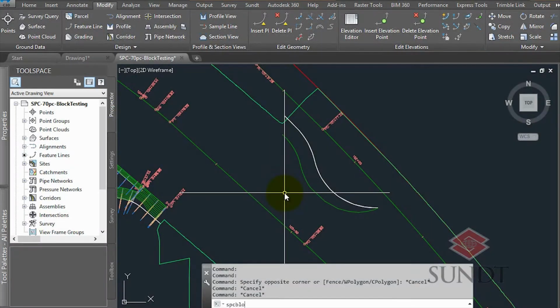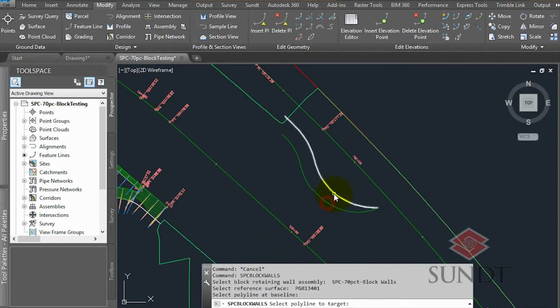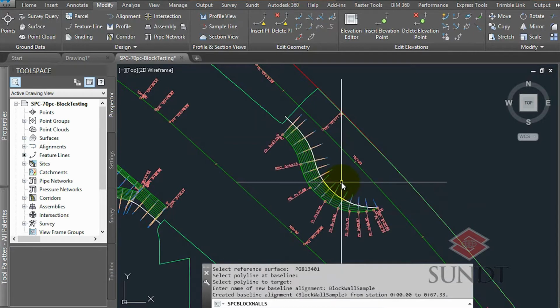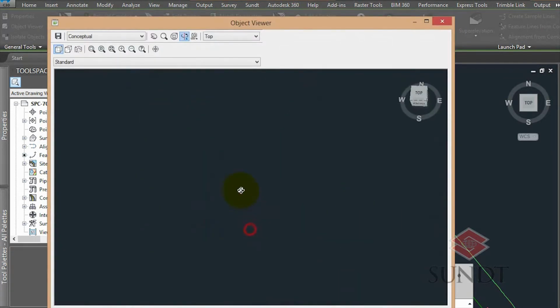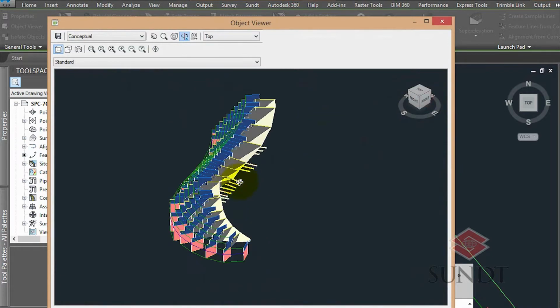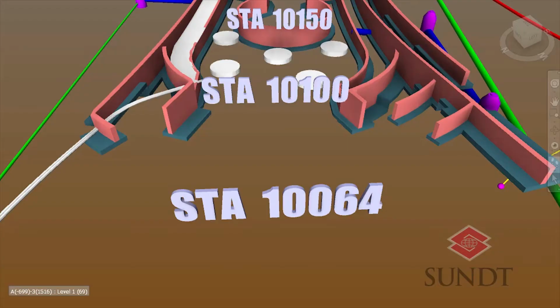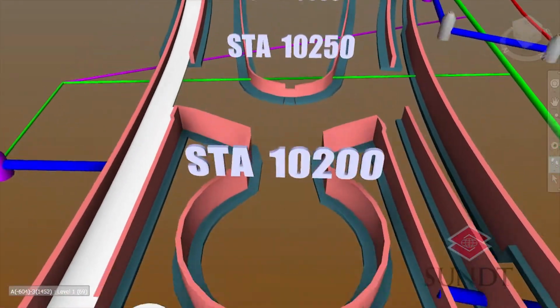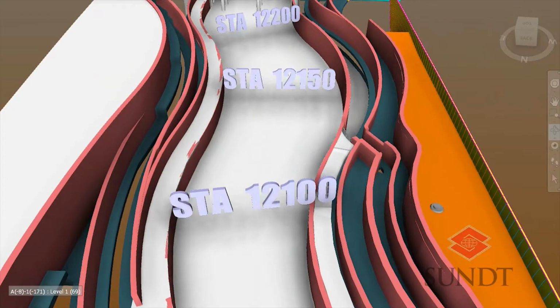Looking beyond construction documents, when a design team provides us digital data, we're able to select design components, just 3D line strings or polylines in 3D, and able to say there is a retaining wall between these two. The software parametrically fills that in. So instead of having to enter data into Excel, we can do it in a few clicks in the CAD environment. And beyond being able to see that 3D model in quantities, we're also able to zoom out a little bit and see the full design at a project level to understand how it needs to be installed or what the specific sequence of work needs to be.